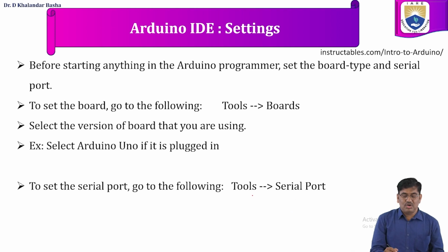Before starting anything in the Arduino programmer, we have to set the board type, as we have seen in the previous slides, the various Arduino family members which exist. We have to select the appropriate board which we are going to use for developing an application. And we have to select the serial port also. To set the board,